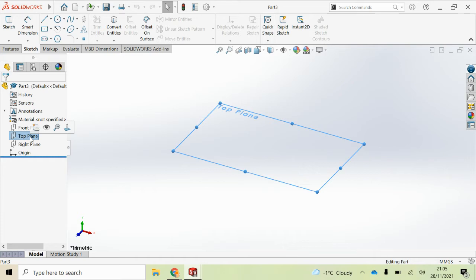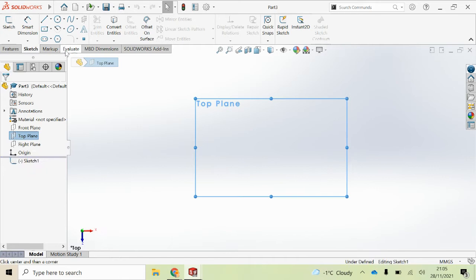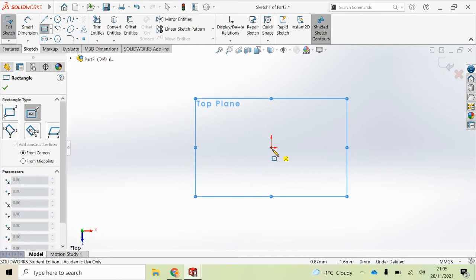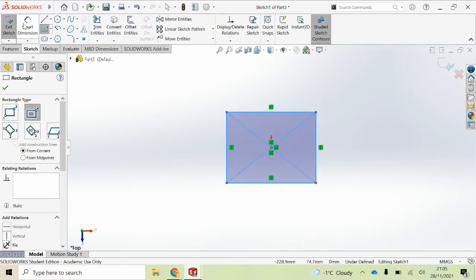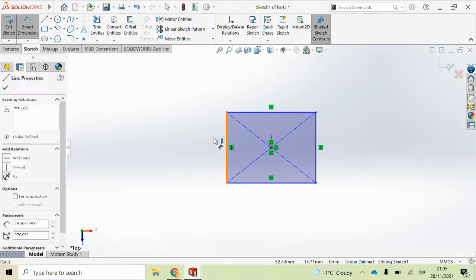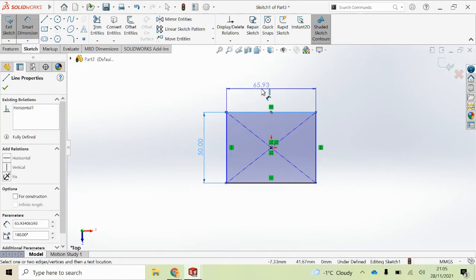most sense. So the first new tool today, so I'm going to Sketch, and rather than using the corner rectangle, which we've used before, we're going to go to center rectangle. As in a previous tutorial, using the origin, I'm going to wait for the little orange dot to appear. Click once, drag it out. So my rectangle is being drawn using that origin as the center. Smart dimensioning all our sketches, as discussed last week. So I'm going to make it 50 millimeters by 50 millimeters.